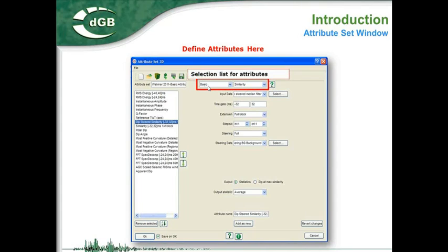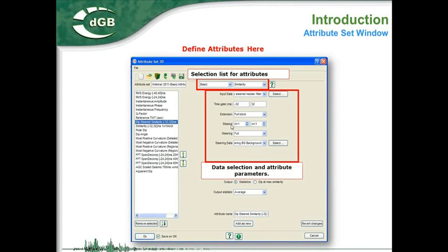So the main theme of attribute definition starts here. On the left hand side you see basic. At this moment it's a group of basic seismic attributes, and I have selected similarity here. When you select an attribute, you get its parameters. You need to provide the seismic data, which is input data. It can be seismic data, an impedance volume, a porosity volume, or any volume loaded in OpendTect. You can select the parameters for that, and then you simply define the attribute and add it as new, and then the attribute appears in the list. So it's very simple.